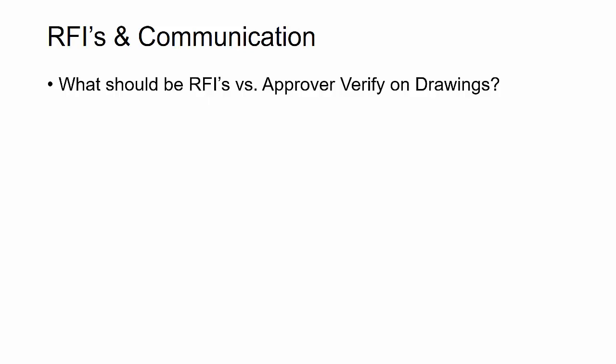And then there are other fabricators that say, hey, no, I want everything itemized in individual RFIs. Send me those and then just clarify and put those RFI numbers on the out for approval drawings if they haven't been answered by approval. So I always ask up front at the project kickoff, how do you want me to communicate? And you want to ask this right away because this impacts a lot of the overhead and management that you have to do as a detailer on your project.